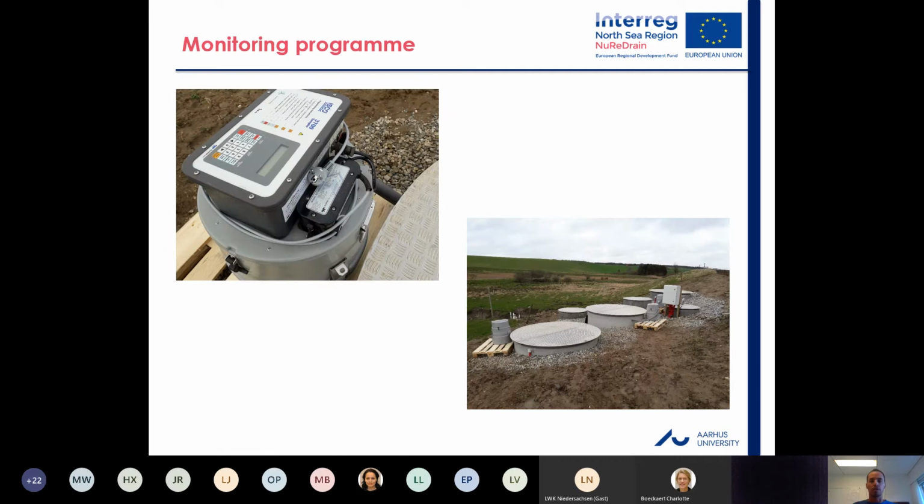The water samples were taken by ISCO samplers, and this is done automatically. The ISCO sampler takes 30 milliliters of water each hour and puts them together into a 1 liter bottle for an entire day. So every 3 weeks, one of our technicians went out to the field to pick up the bottles, which were brought to the lab and analyzed for pH, electrical conductivity, TP, total phosphorus, dissolved reactive phosphorus, and turbidity.